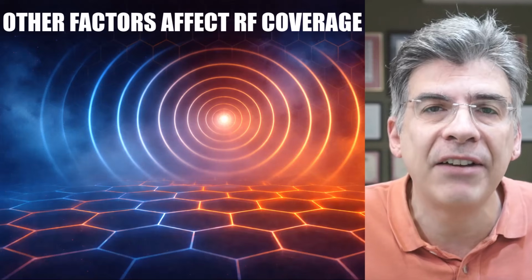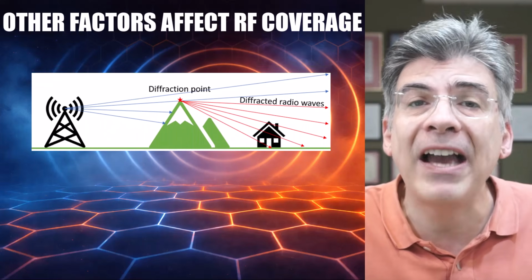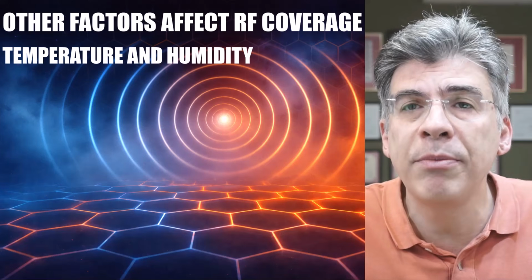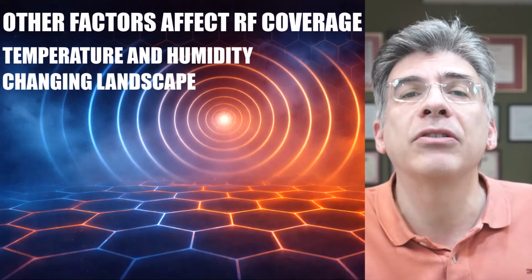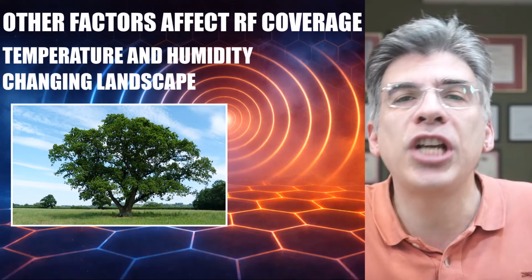Now, for those of you that are familiar with wireless technologies and how radio frequencies behave in free space, you'll know that the tilt of an antenna is not the only thing that affects optimal coverage. Continual changes, both short-term and long-term, in the environment around the antenna can affect the way RF signals propagate and how they are distributed. Changes in temperature and humidity affect how signals are distributed through space in the short term. The changing landscape also affects RF signals. Deciduous trees in winter have no leaves, while in the summer their leaves become barriers for RF signals. These are seasonal changes in the environment.